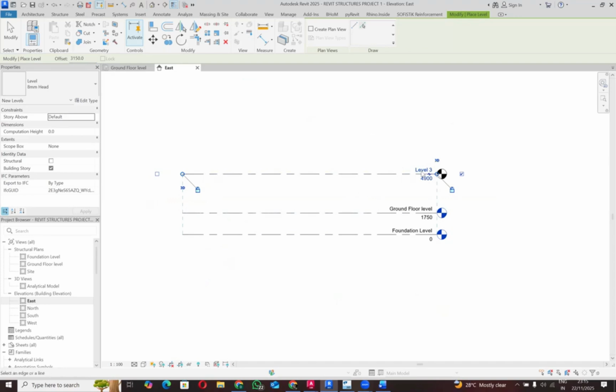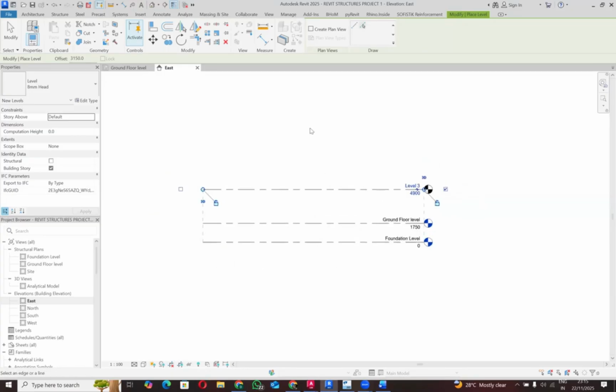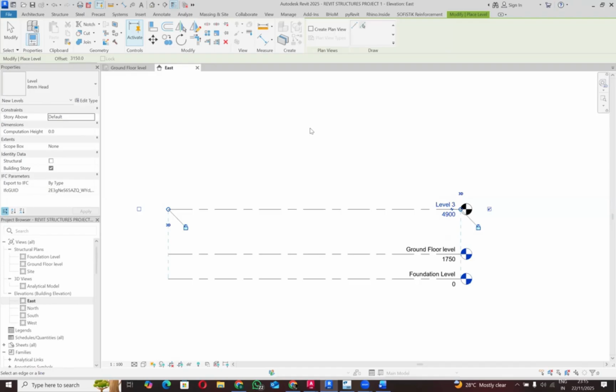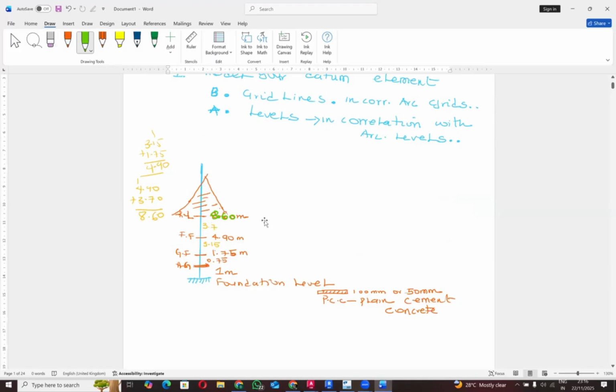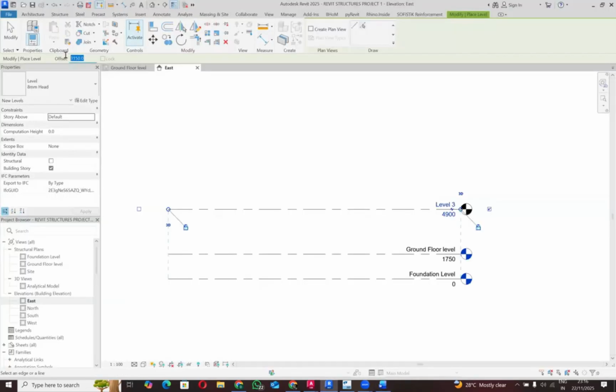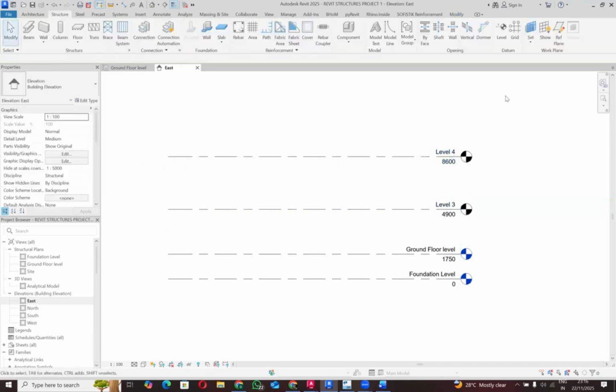You can decide to draw all the gray lines before you come and edit the names. So you pay attention to that very carefully and have your modeling methodology which you feel makes sense to you. So let me model all the lines before. The next one is 3.7, the roof level. You just change it to 3.7, then we hover up and select. You have it 3.6. So you have your level 6.